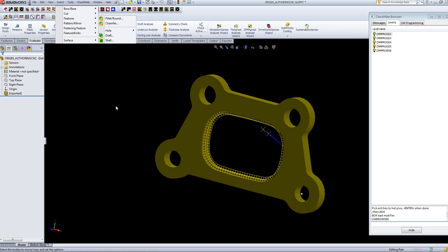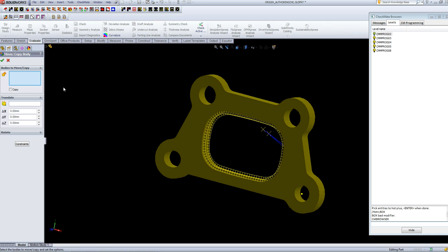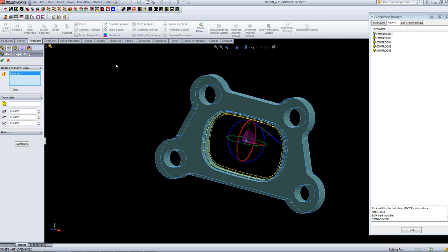If we click on that, of course, over on the left here you can see it wants to know what body we want to move around. So I'm just going to click the part, and you can see the whole thing gets outlined here. What you see over on the left side is there's an option for translate, and there's another one here, the little drop down for rotate too. Even if there were some rotation coordinates you needed, if you want to move the part around by an angle. But we're just going to do a translate. So I believe it was minus 19 and 52.1.